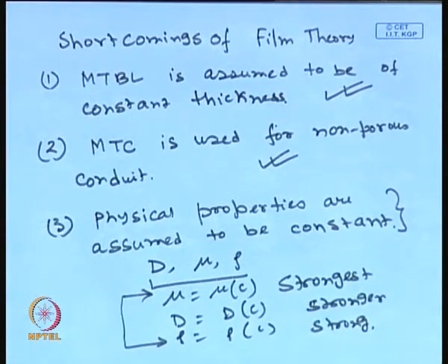So, in gel layer control filtration, the variation of concentration in the concentration boundary layer from C0 to Cg is maximum, and in osmotic pressure controlled filtration also, within the mass transfer boundary layer, it gives a significant variation of concentration. Therefore, the property variation has to be taken care of in the model. So, how to do that?